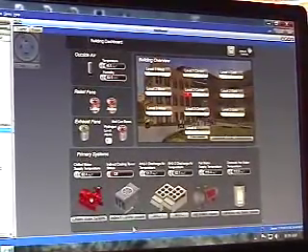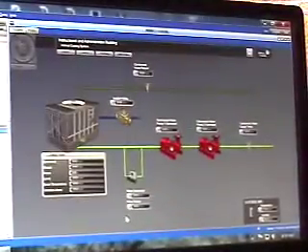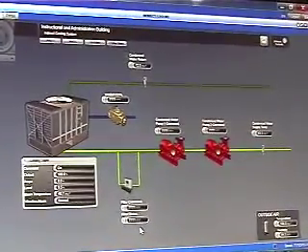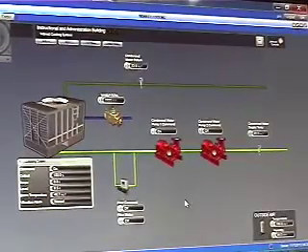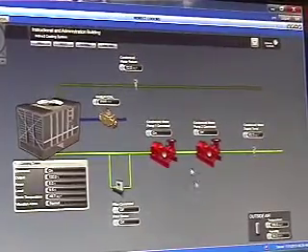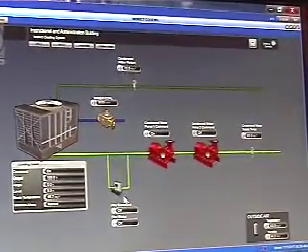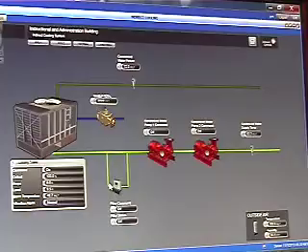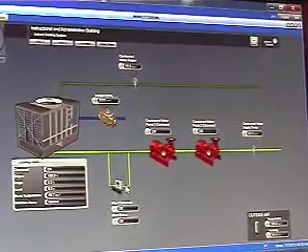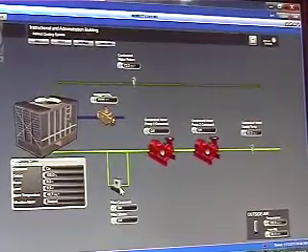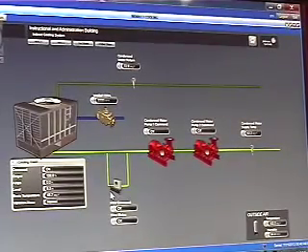Cooling tower right here. Indirect tower, this is the dedicated tower out at the building that just serves those 2 air handlers. So whenever there's a call for the system to run, it enables the fans and everything to turn on and run. You do the same thing with these pumps here. Filter command. So here you have the 2 pumps. You have the solid separator, or cooling tower filter, whatever you want to call it. Whenever either one of the condenser water pumps are on, that solid separator is also enabled to run as well. Whenever the pumps shut off, the solid separator disables as well.